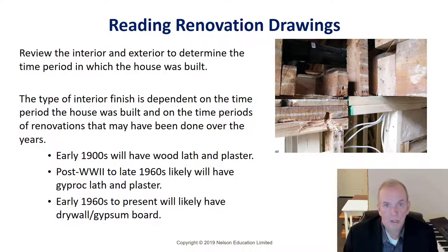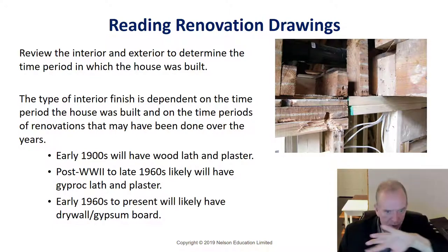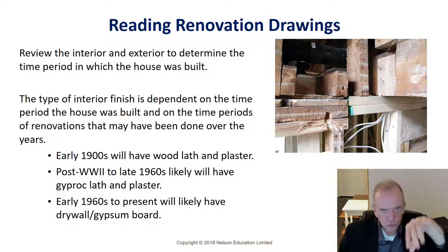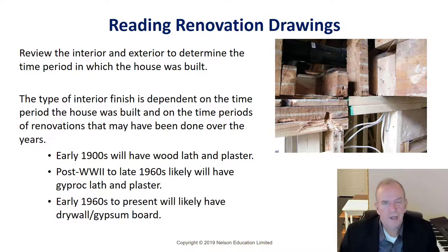Plastering required 3 coats. You had to put on what they called a scratch coat, because they would trowel it on and then they'd run this little sort of wire thing over it that'd scratch it so it'd roughen the surface. Then they'd put their finish coat, right? And they put that over it. They called it the brown coat. And then over the brown coat, they put the putty coat.